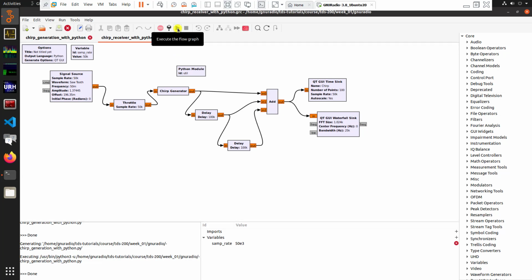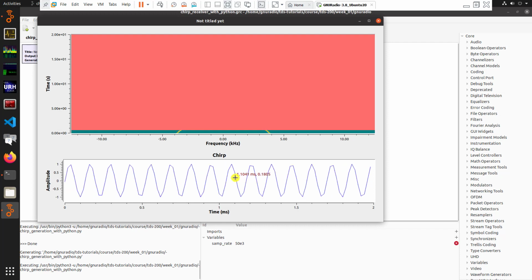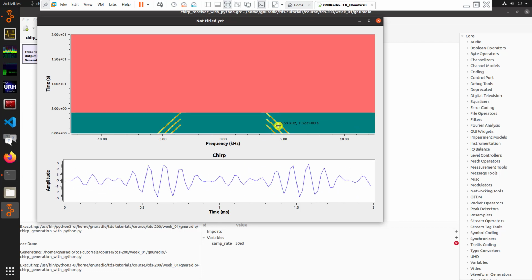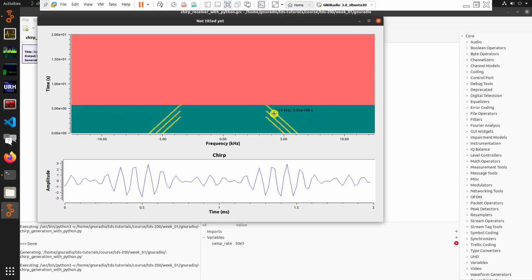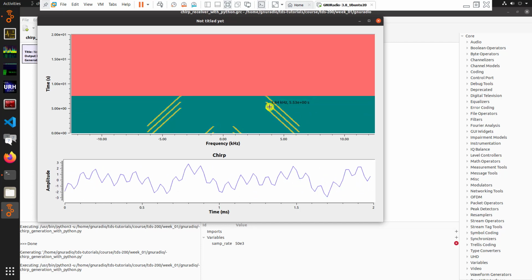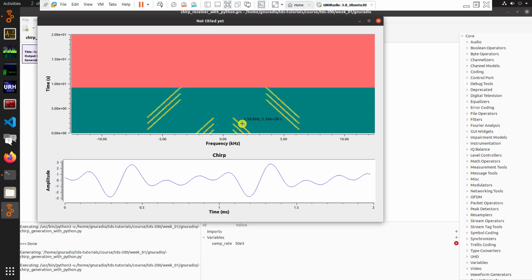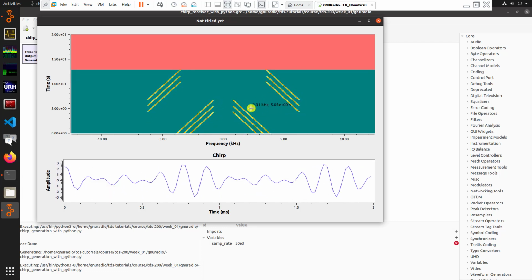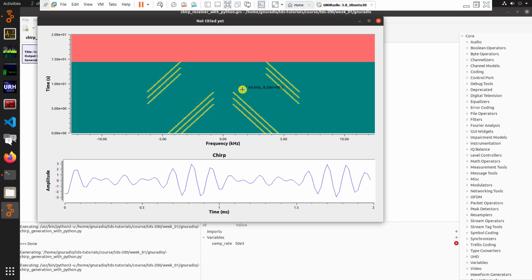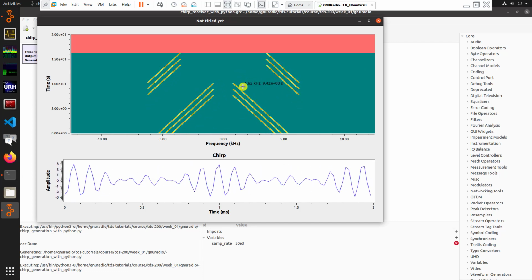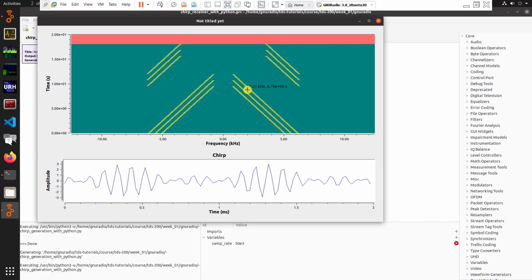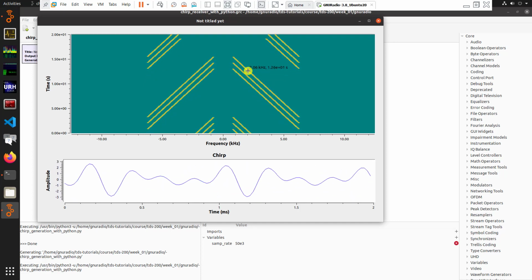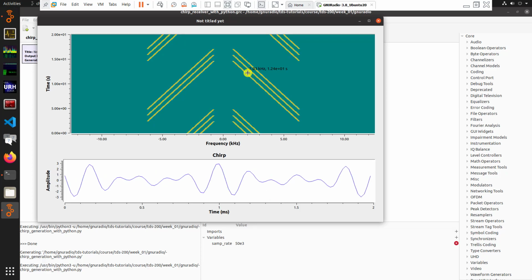we can then execute the flow graph, and what we see again is our chirp waveform, but now instead of just that transmitted copy, we also get the delayed copies from object 1 and then object 2, and then we can see that this repeats again. And so we have a way in GNU Radio to take the existing code and simulate what the transducer would receive if there were two objects equally spaced at equal intervals from the transducer.